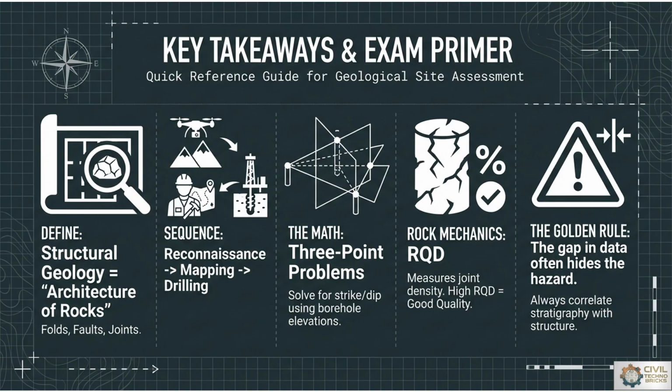What are the key takeaways from that subsurface geological exploration? That is, define structural geology, which is the architecture of rocks, which shows the descriptive part or the nature of faults and joints. The sequence which is followed for the surveying, that is the preliminary survey from reconnaissance to mapping and drilling based on some remote sensing, GPS, GIS techniques. The mathematical calculations based on some interpolation or trilateration method just like 3-point problems which solve the strike or dip angles and direction using borehole elevations.